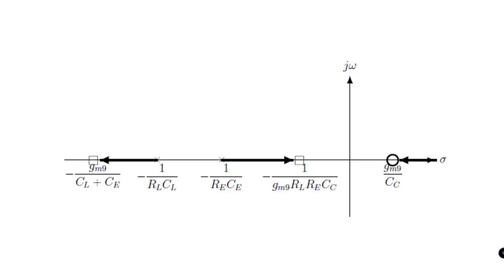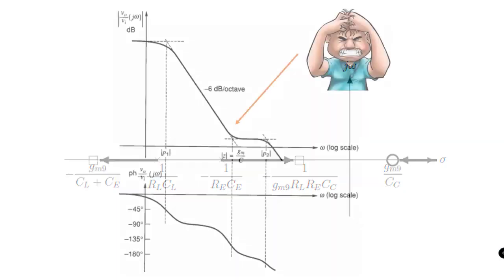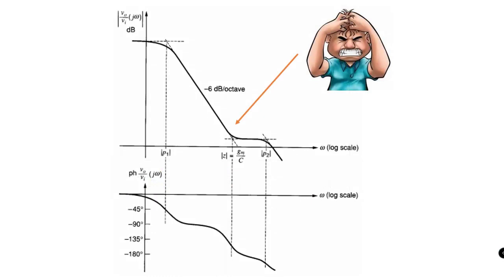Now let's visualize the impact of the 0 in the frequency response plot. One could note that for a feedback factor of 1 at gain crossover frequency, the phase value becomes much lesser than minus 180 degrees, which would make our system unstable for a feedback factor equal to 1.